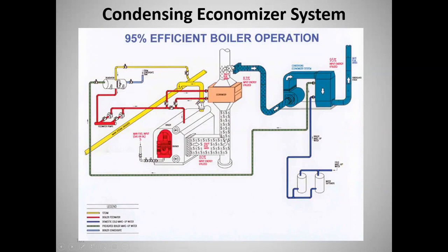And then we pull off over here and we come down, and we do have another fan system. And then we've got our makeup water. We have cold water coming in here that is then pumped across this coil. So then we preheat it a second time, and then this is going back into the steam system. Now, this would be for a situation where maybe we're not returning hardly any condensate.